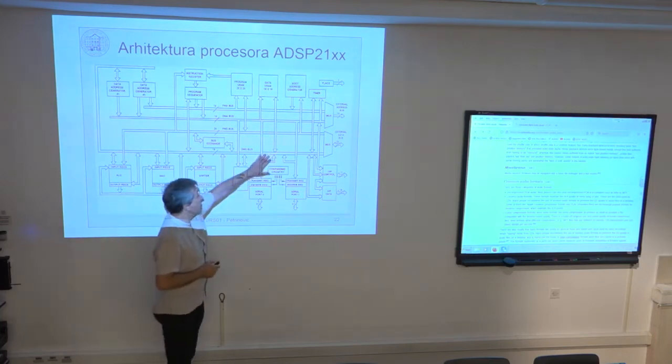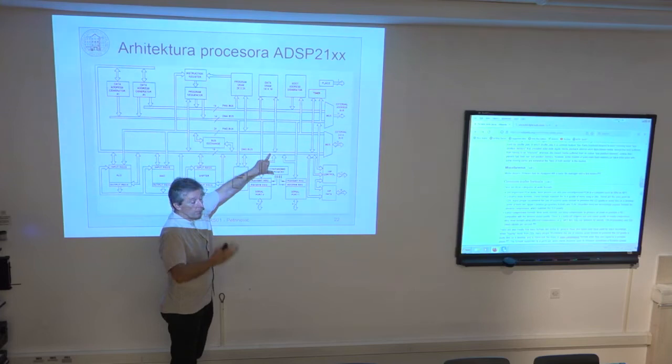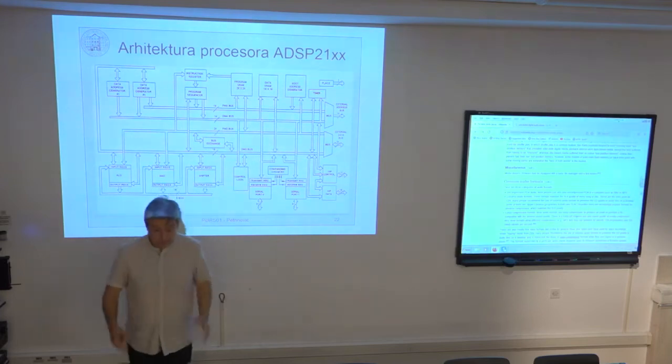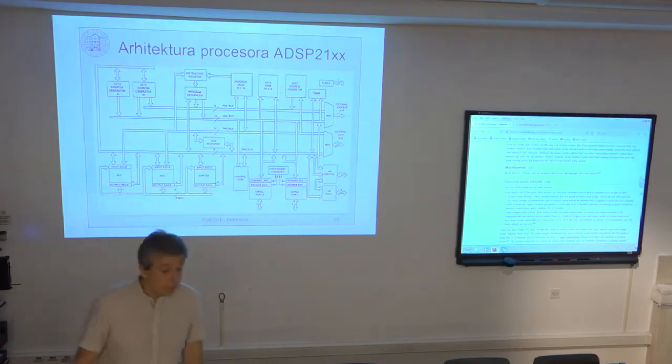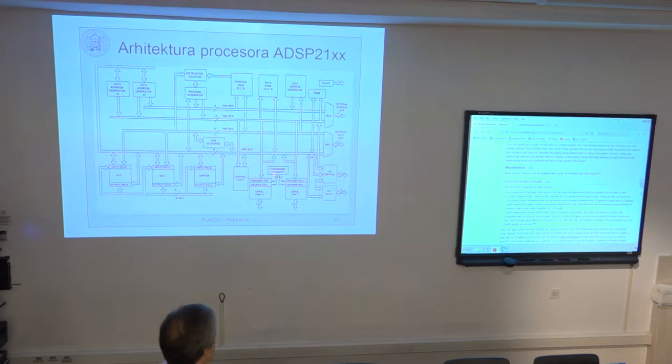This one is 16 bits wide because the native argument width is 16 bits. So the data path is 16 bits wide for the ALU, for the MAC, for the shifter. For that reason, the data memory data bus is as well 16 bits wide, to be able to fetch the whole short value from the memory. At the same time, the program memory data bus must be 24 bits wide because the instruction is 24 bits.